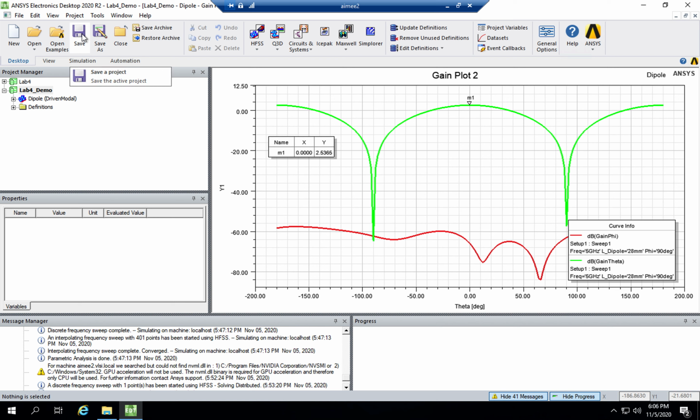All right, so a horn antenna is simply a waveguide that's flared in order to match the waveguide to free space, and in the process radiate the energy to free space. The idea of a horn is fairly straightforward, and it's one of the oldest antennas that were designed. You have a waveguide, and you flare one end of the waveguide in order to match that end to free space. And as you know, if you have perfect matching, you basically transfer all the power. So in that case, the horn will radiate all the power from the waveguide to free space.